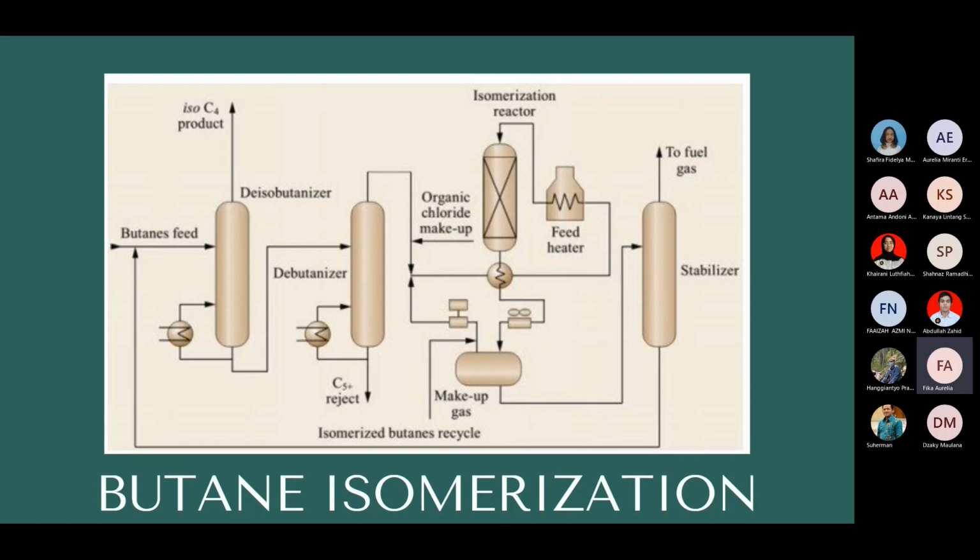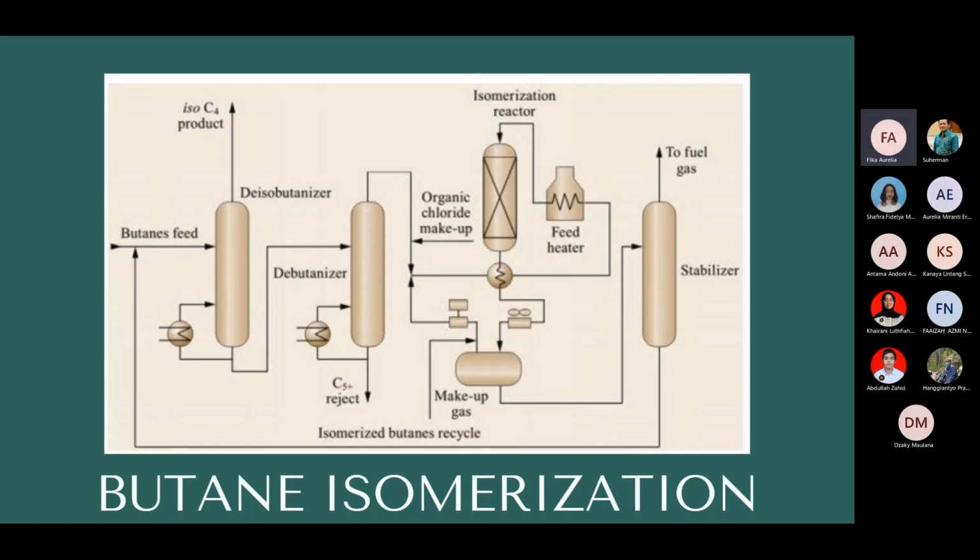Because the catalyst is extremely sensitive to moisture, the feed must be completely dried before use. The catalyst in the low-temperature first step is aluminum chloride promoted by hydrogen chloride. Hydrogen gas is then used to prevent the formation of olefins and to manage side reactions including disproportionation and cracking. The catalyst in the high-temperature second stage is a noble metal such as platinum.